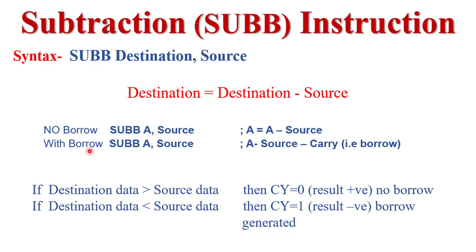First we know why we require the subtraction with borrow instruction. The answer is, when we subtract a larger number from a smaller number, we require a borrow, and the flag bit of the PSW flag register is affected depending upon the result. Again the question arises, do we have a borrow flag in the 8051 microcontroller?